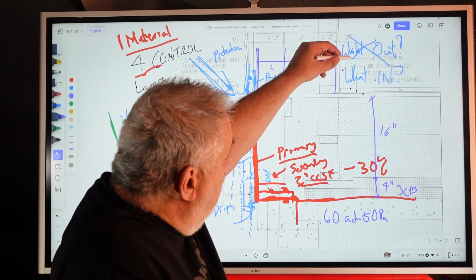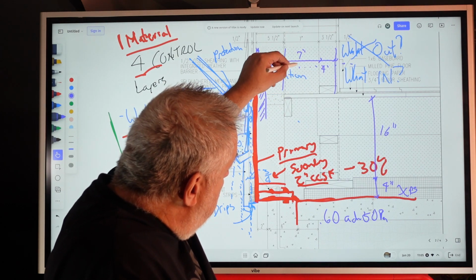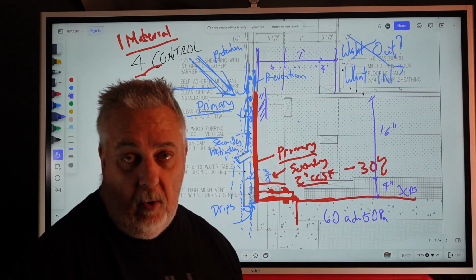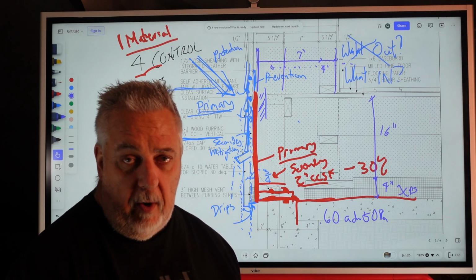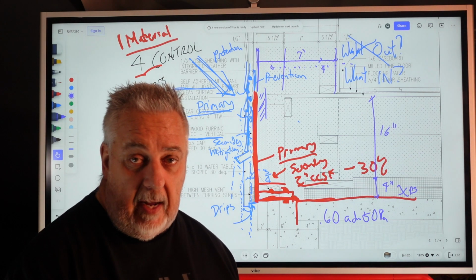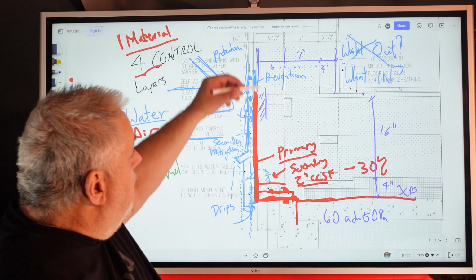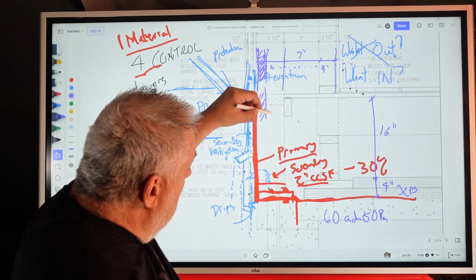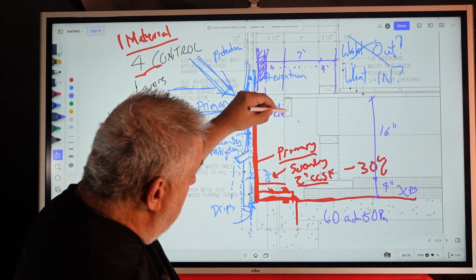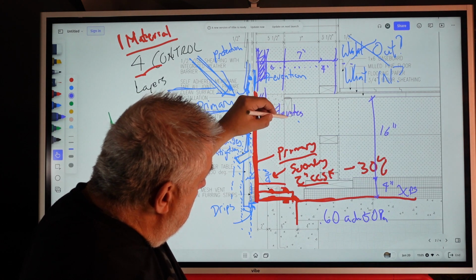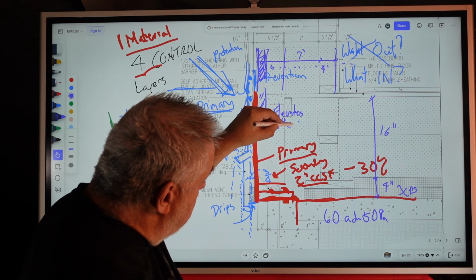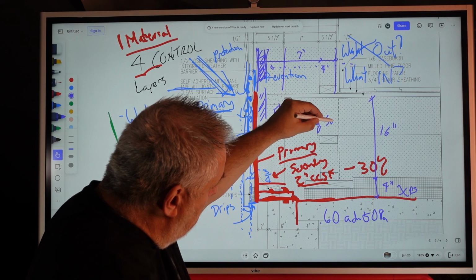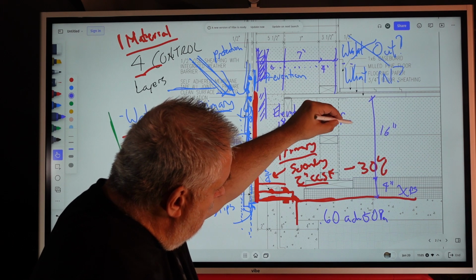So as moisture diffuses through here, it is looking for a cold surface. Well, it's not looking for it, but when it finds a cold surface, it's going to condense. And so the 2 inches of closed cell that we put here elevates the first condensing surface. Right?